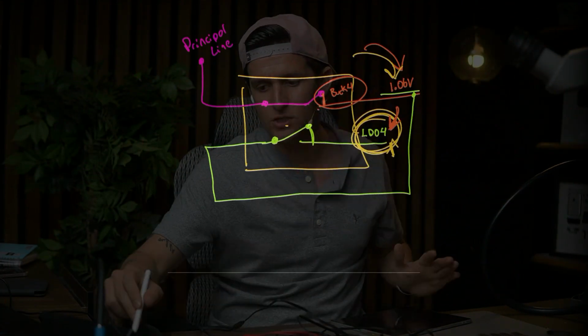So that's why it's so important to understand these little basic things about PMU. Because if you understand this, now you say, okay, I don't have this buck, but which line provides the power to have this buck or this LDO? If I don't have this LDO, I have to check first which line is providing voltage for having this LDO. Okay, this is so important to understand.